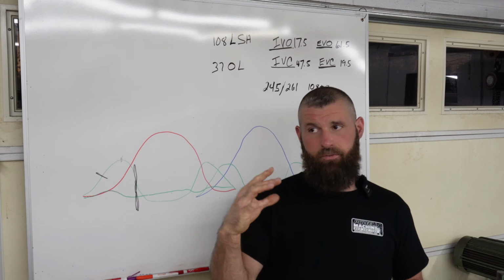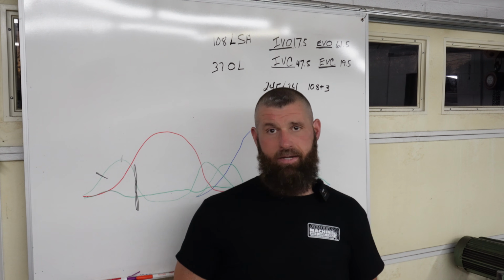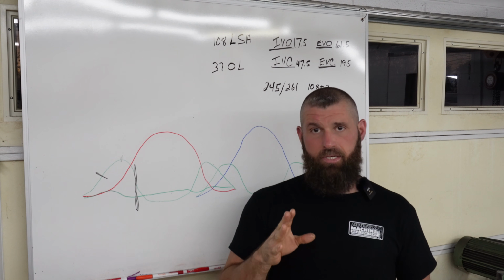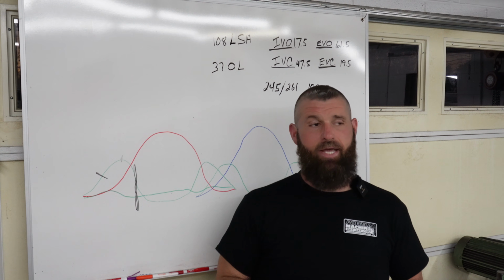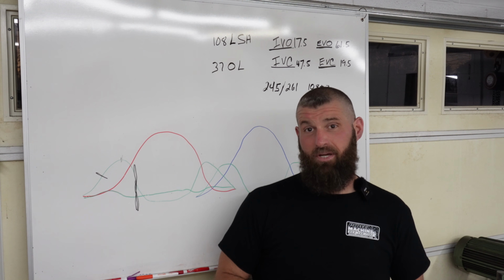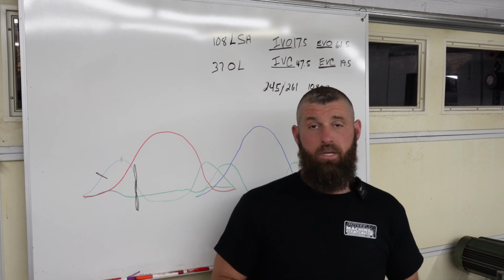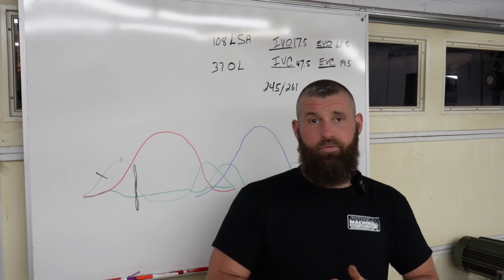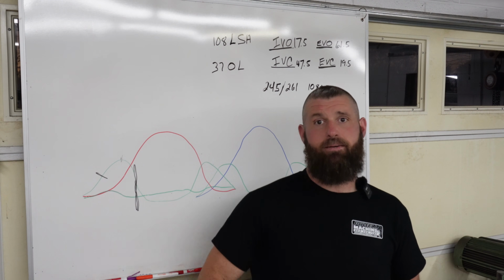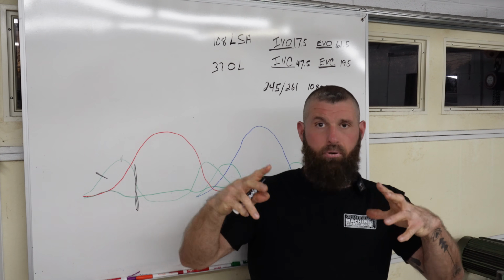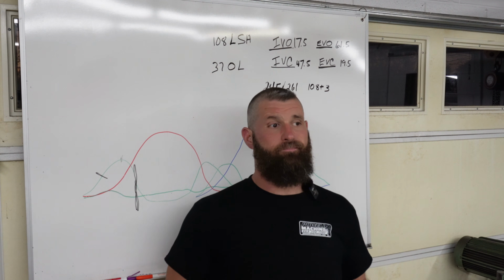You take that same motor and pull 25 CFM out of that cylinder head, and now that same motor, to go to 7,000, is going to need 18, 19 more degrees of duration to do the same job. So then you'll see that down low, the torque's going to be off just because the cam is so much bigger.